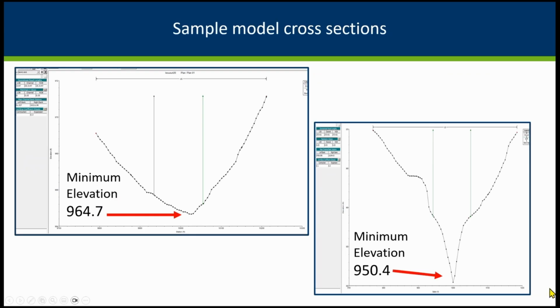And then other times there are models where a lot of these zone A models are only using the available LiDAR, and LiDAR can't penetrate water surface elevations. So that LiDAR is only going to grab the top of the water surface elevation of the stream. It might be missing the deeper part of the channel. Sometimes that channel can be fairly deep, but it might be a fairly deep, narrow channel that's just being missed, and you're missing a lot of conveyance through there. So sometimes if you're adding in more channel information, or just making the shape look a lot more like what your valley cross section looks like, that can change the results fairly dramatically. Next slide.